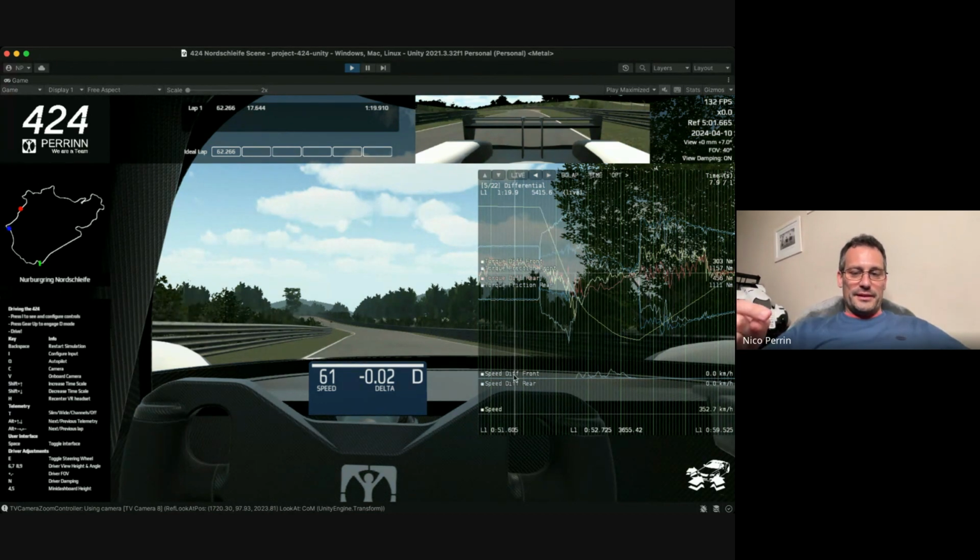This is the speed differential across the left and the right wheels. I'm going to hide the rear. This is the front. When it's 0, it means the diff is locked. There is no speed differential left to right. You can see up to this point, up to the middle of the braking, the diff is fully locked. And the reason, again, is because we have a mechanical diff that locks proportionally with the torque we apply on the diff.